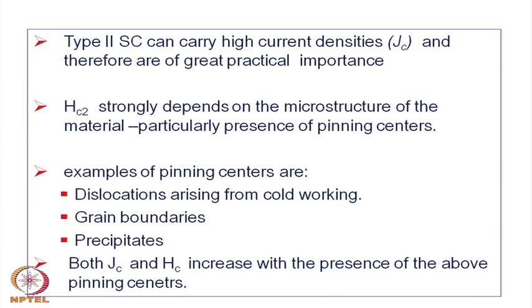Both elements or metals and intermetallics have a certain amount of elastic deformation, and beyond the elastic limit, plastic deformation. In fact, in case of metals it is much more, whereas intermetallic compounds are a little harder and relatively brittle. However, even then one can cold work it. Cold work is a metallurgical term basically. It is allowing the material to deform plastically under high pressure.